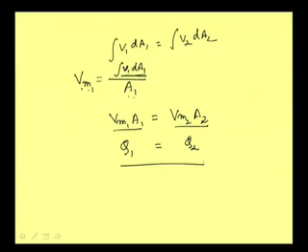Well, now when we write this sort of continuity equation, we should remember one point, that the velocity we are using, that is V1 A1, this V is the average velocity or mean velocity. Now, in a very simple way, this is for a steady situation that we are writing this equation, and that is why the use of all those theorems is not coming into this derivation. Well, now let me see what about the momentum equation.